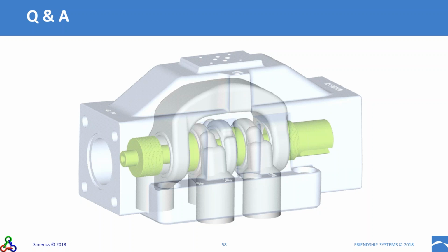That makes it very robust in the variation. Our focus in the end is always to vary the geometry. That's the difference to other traditional CAD systems, where you can build all kinds of geometries, but it's very difficult to vary them quickly and automatically. And that's our focus. So we have to put in some thought when we build up the model so that it is suitable for this automated variation.